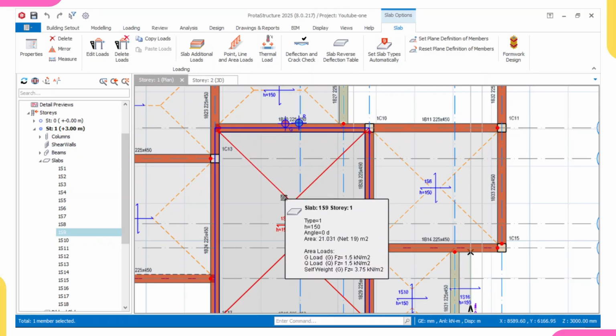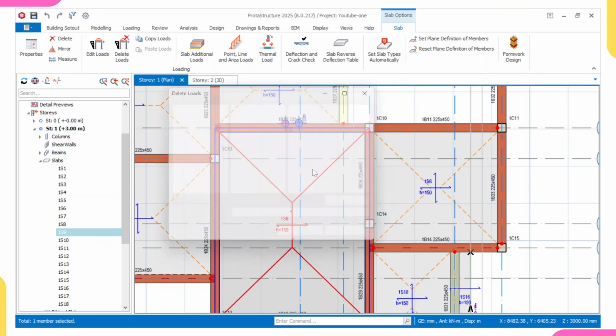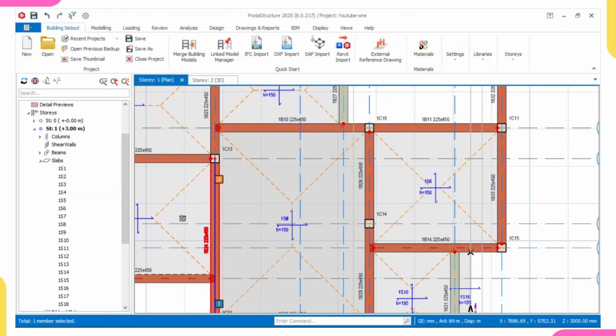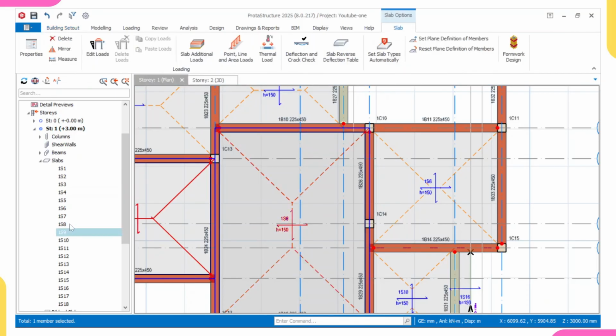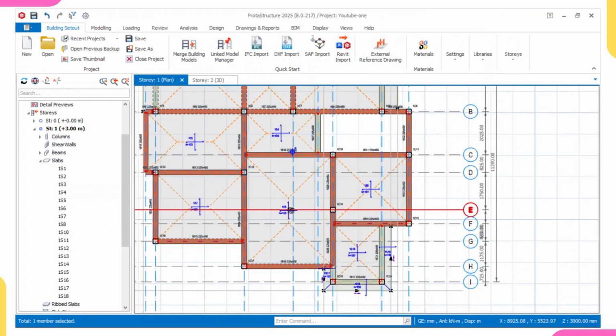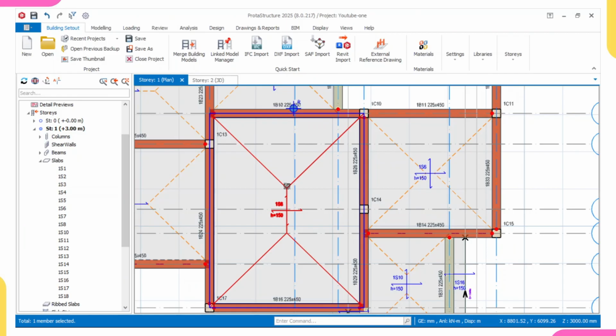So this is the reason why you should be doing your building model analysis. So I'll just right click and delete one. Delete. You see, I've deleted one. Sorry, let me delete it again. Right click, delete. I have deleted one. As you can see, this is the reason why you should do your building model check, to know whether everything is correct. Assuming I went on to do analysis, all these beams will be failing because load from slab 8 and slab 9 will be coming to them, because these two slabs are applied on this.